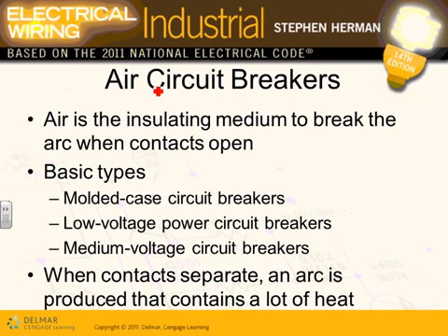The tripping mechanism in any circuit breaker, we talked about thermal, we talked about magnetic. There's also electronic, guys, where you can sense the current electronically and make a decision. That's called electronic circuit breakers. You're looking at a thermal circuit breaker right here, and the circuit breaker right at the top of it is actually an electronic circuit breaker. Can you see that adjustable? This electronic circuit breaker you can adjust. So there are electromagnetic, thermomagnetic circuit breakers, and electronic circuit breakers.